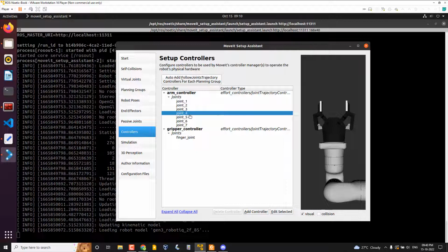Yesterday we discussed the controllers inside MoveIt, right? So basically, when you press the execute button, MoveIt is a controller client, and Gazebo or the real robot is acting as a controller server. So this MoveIt client is sending a trajectory to the server. It can be Gazebo or it can be the real robot. So this trajectory is going to be sent. Okay, so we have to keep a configuration on the MoveIt side to send the trajectory to Gazebo or to the real robot.